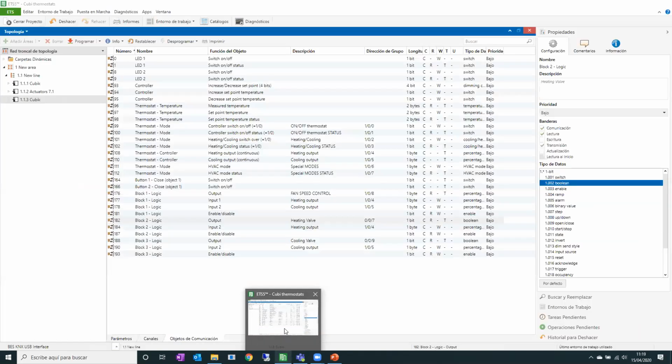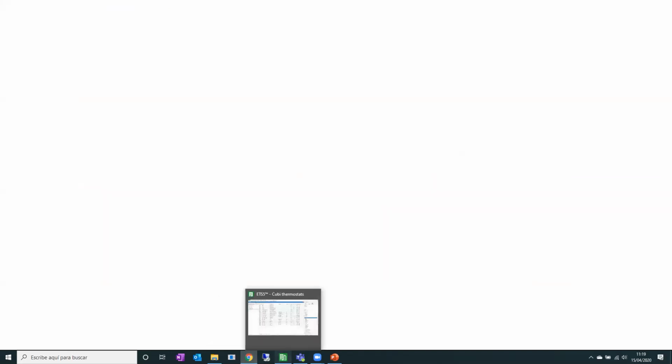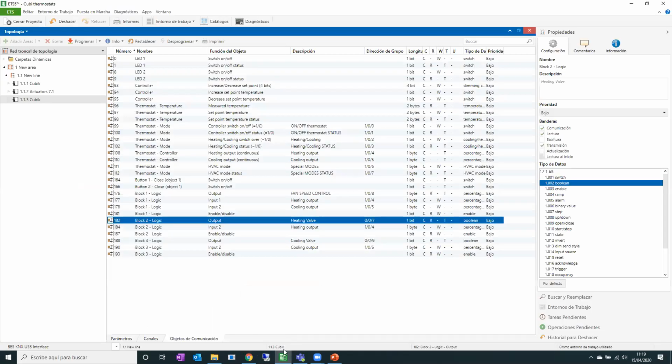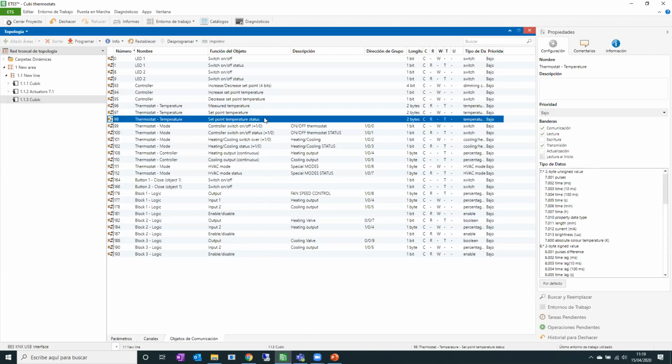Okay, let me show you. With the climate gateways, like the Daikin gateway that you mentioned, you can also send the set points to the split machines. Yeah, set point is fine, but how about mode? With those gateways, you can also change the modes in the machines.